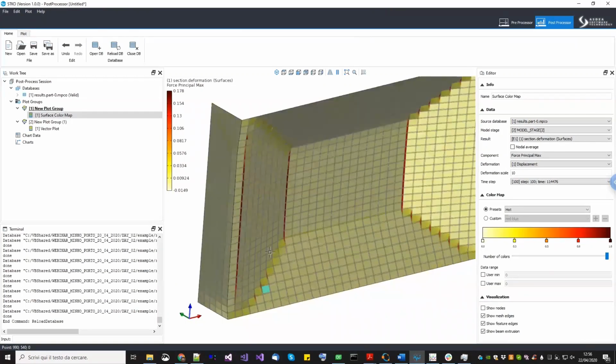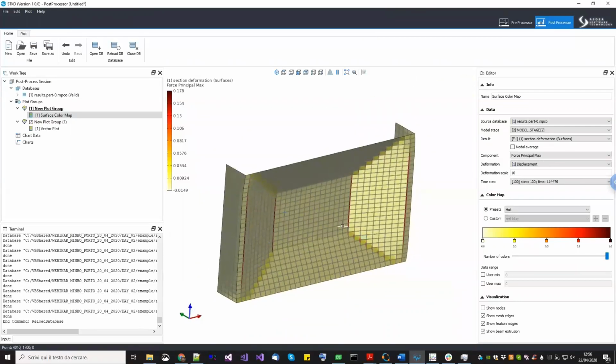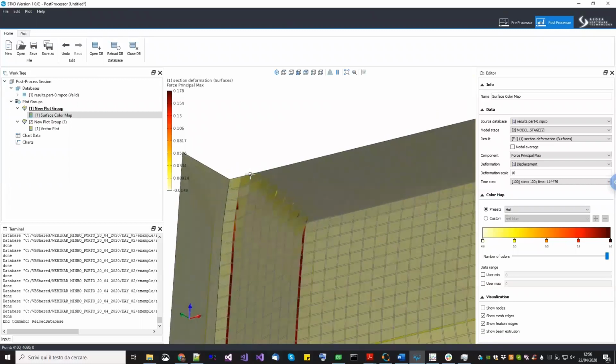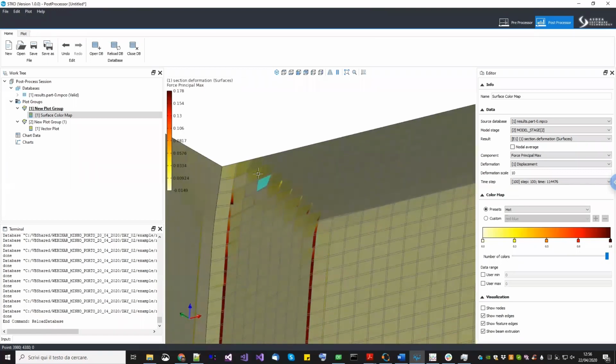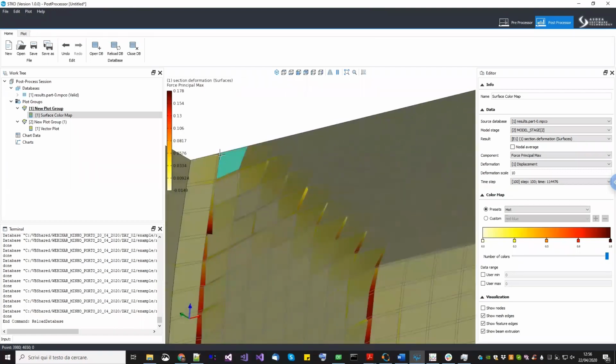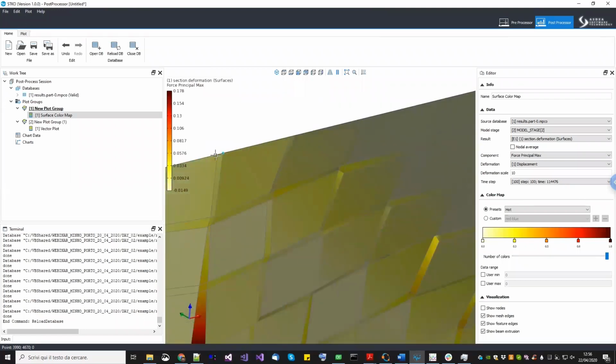The problem is that when people in finite element talk about the typical size of a domain, they do not refer to the entire structure actually. They refer to the typical size in which the displacement field remains continuous. Now in this case, the displacement field has high jumps even in the dimension of a single mortar joint.